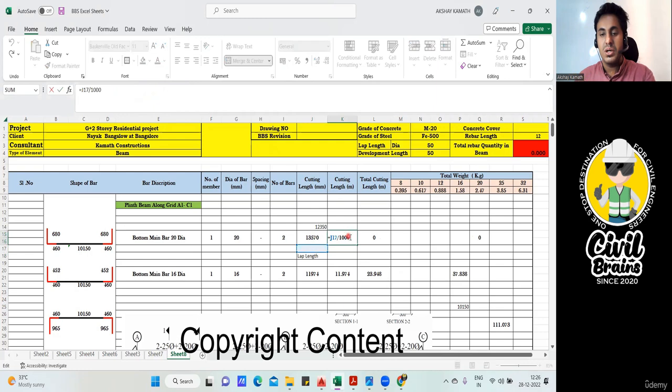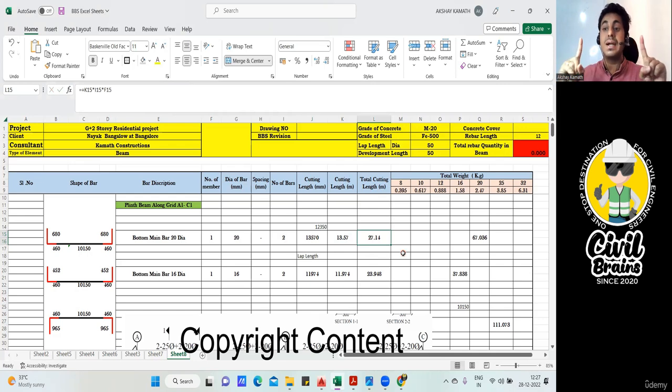I'll convert this into meter. So I'll select this one and divide it by 1,000. So 13.57 meter is the cutting length of one bar. How am I going to find the total cutting length? Total cutting length will be cutting length of one bar multiplied by number of bars into number of members. So 13.57 multiplied by 2 multiplied by 1 will give me 27.14. So this is the total cutting length of 2 bars of 20 diameter.